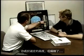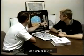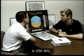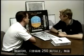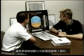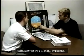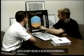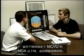Okay. You're at the selected altitude and you deviate more than what, the box will turn amber. It's 250 feet. Will you get the altitude alerting then? Yeah, anytime you deviate by more than 250 feet, regardless of the autopilot, you'll get an alert. Is there any other time that the numerical value might go amber? Yeah, it's similar to the whole decision height and problem down here. When you descend below an MDA that's set in the MCDU, these will turn amber.